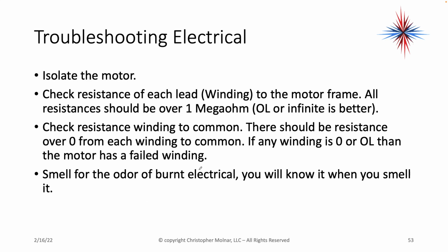Smell the motor for the odor of burnt electrical. You'll know it when you smell it. It smells like melted plastic and something else combined with it, but you'll know it when you smell it. Okay, if that's happening, something is starting to burn out. Even if you haven't gotten bad resistances, there's something wrong.